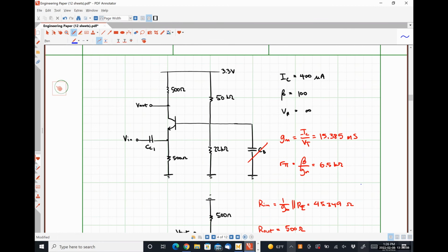If we only have access to a 3.3 volt source, the correct way to bias this is to choose the resistors such that we get a bias voltage of whatever we need to drive our particular amount of current for our amplifier, right? If we don't have these resistors, we have to replace this resistor network with literally some form of battery or something like that, which doesn't make any sense. So the capacitor here keeps the DC bias point stable while also eliminating this base resistance from our small signal analysis, therefore eliminating that reduction in gain that we observed a moment ago.